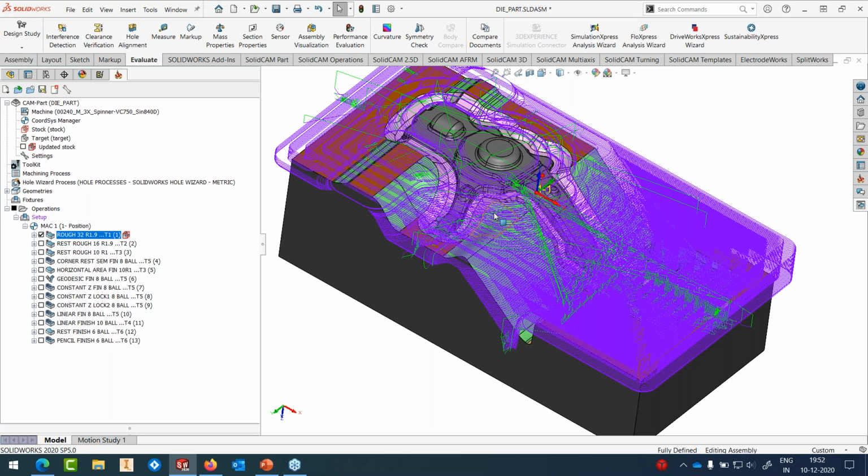we have got an option to define whether we are using a center cutting tool or not. If you have defined a non-center cutting tool, it will make sure that it will not ramp at all on your part. So wherever areas which need ramping, they will all be skipped. It will not machine that part at all, or that area at all.